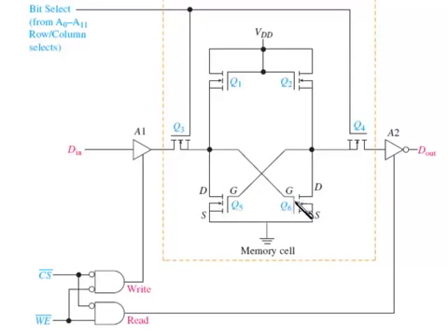Now when we want to read Q6, or the 1, to the output, we take the chip select, keep it low, and make the WE high. That enables this line, which enables this buffer. Now the 1 that we put in here is actually going to be a 0 felt at this point. That's going to come out, and that's why we need an inverter at the D out, because remember, to put the 1 in, we actually turn Q6 on.